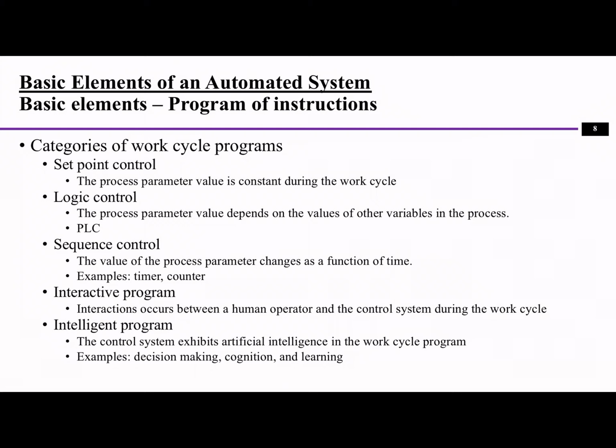While another, a little bit more complicated logic, for example, in the transfer line, we can use a sensor to detect what type of product it is. Say the color. If it is yellow color, it goes to route 1. If it is a red color, it goes to route 2. If it is blue color, it goes to route 3.